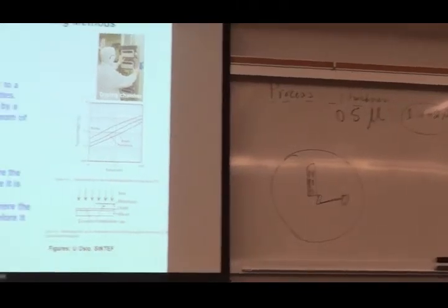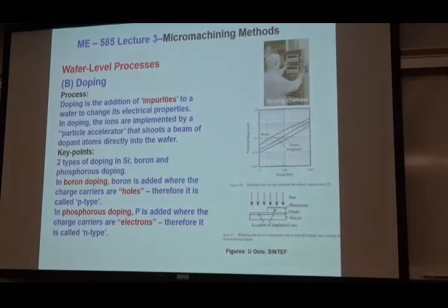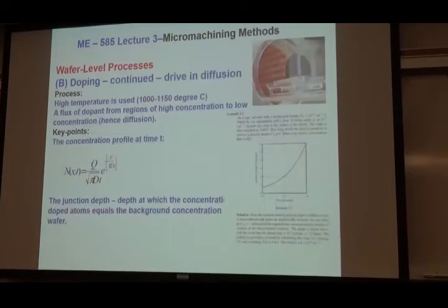Okay, so doping, very easy. High temperature, typically greater than 500 degrees. So it depends, but you could do it greater than 500 degrees Celsius. Boron and phosphorus have to be in a gaseous form. Pressure, ambient pressure. Okay, it does not have to be vacuum.